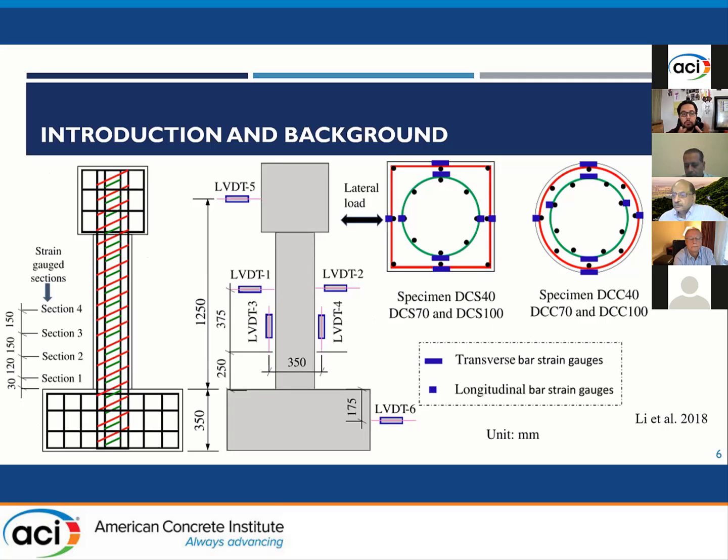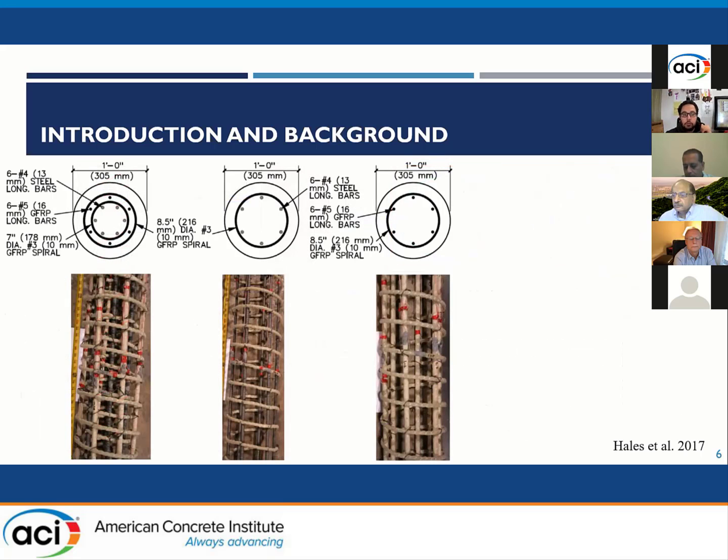Unfortunately, this work has been done on steel sections, where the longitudinal reinforcement is made of regular steel and the spirals are made of high strength steel. But it did prove the concept in terms of the deformation capacity and how much it was enhanced by having double layers of confinement. Something like this may be closer to what we are suggesting, with steel at the inner layer and GFRP at the outer layer, but these specimens were tested on a smaller scale and only under axial load.